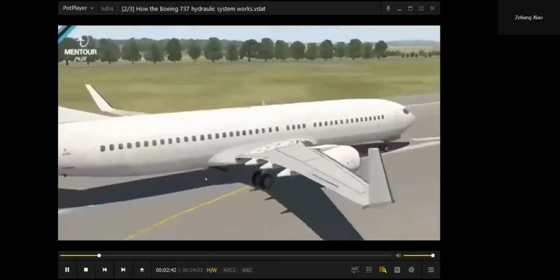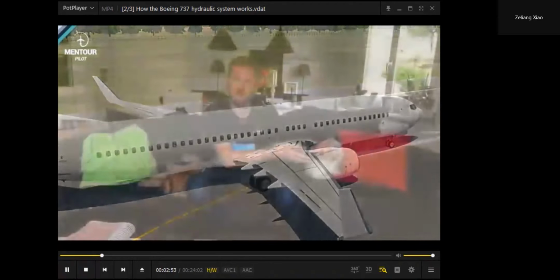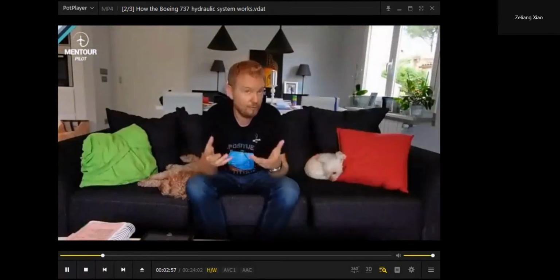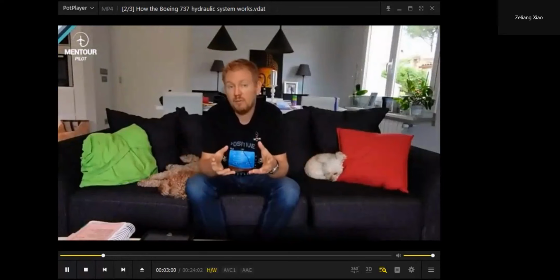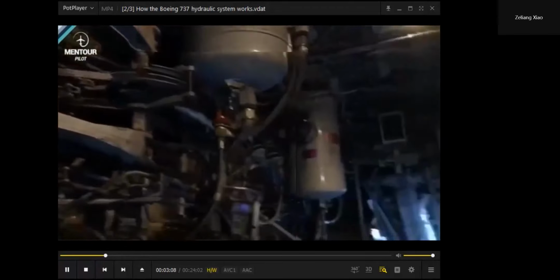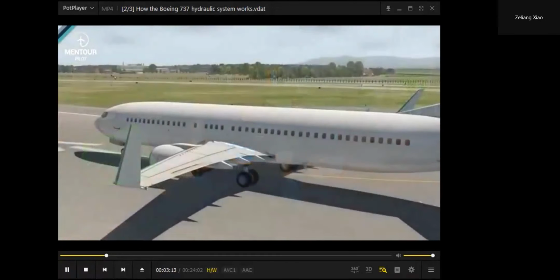There are different ways of doing this. However, the hydraulic system has a very unique way of being able to create the force needed in one place and exert it in a different place, without using bulky equipment where you actually need to exert the force. So for example, all of the hydraulic pumps are either in the engines or inside of the central wheel well bay, but the actuators, for example for the ailerons or for the rudder, are where they are, right?